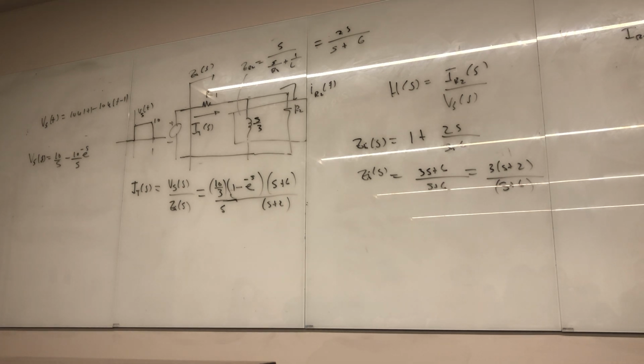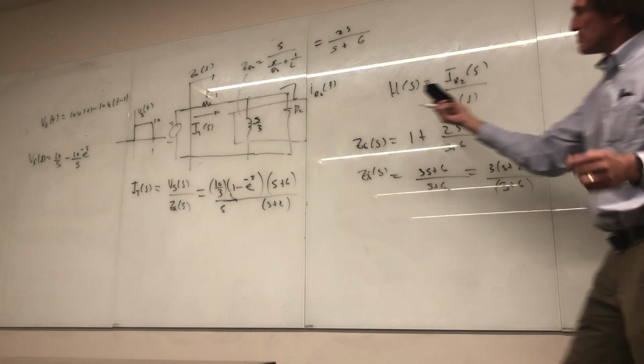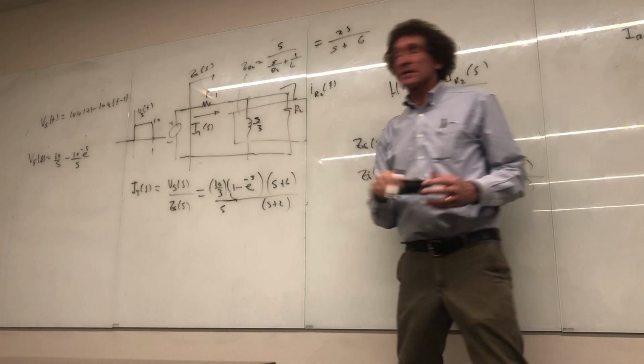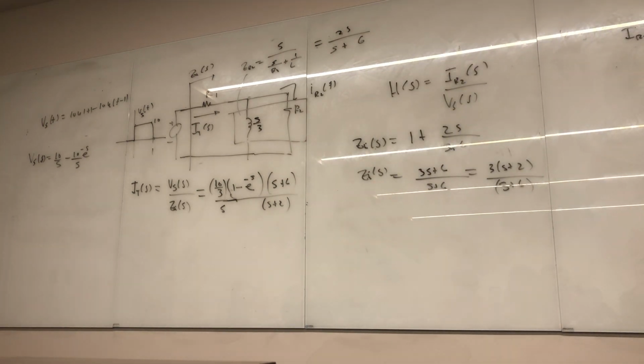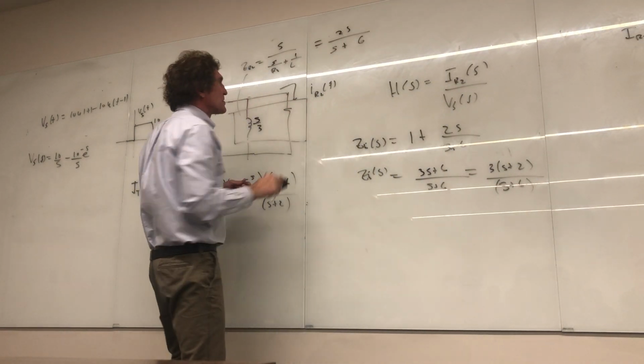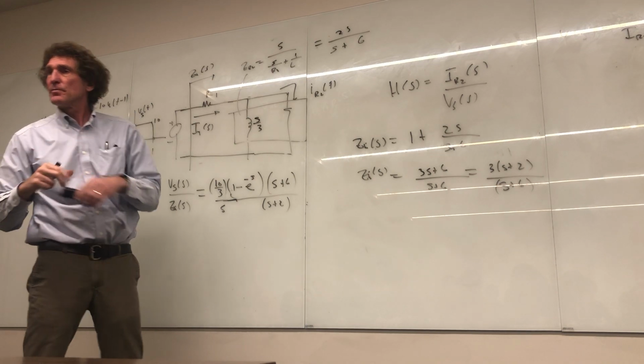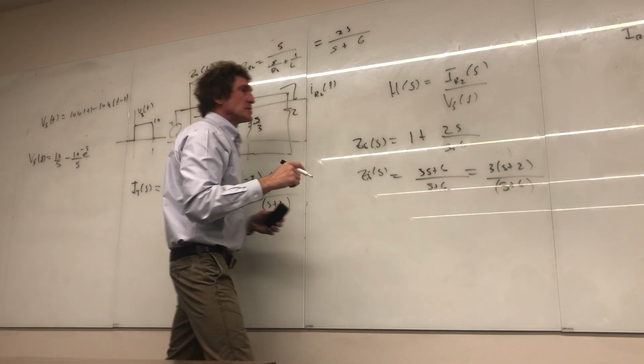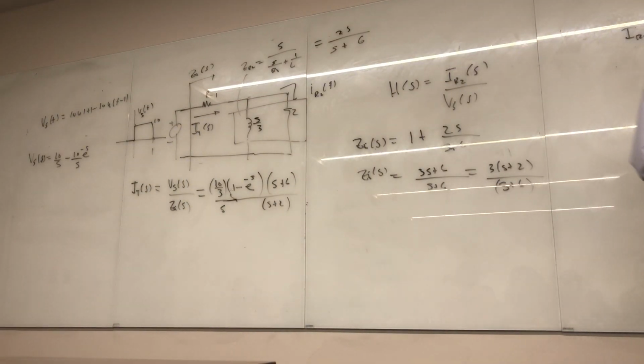And that's an S. And I'm going to take that and I'm going to multiply it by the opposite impedance, which is this, S over 3 over the sum of these two. And R2 again was 2. Just put in a 2 there. So now it's going to be S over 3 over S over 3 plus 2. And that would be I of S. Do you all agree with me here? How many see the way I'm doing it?